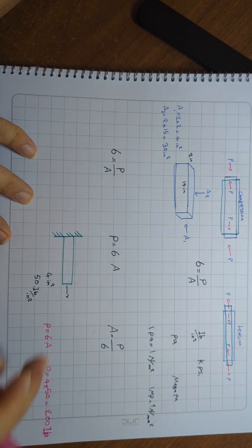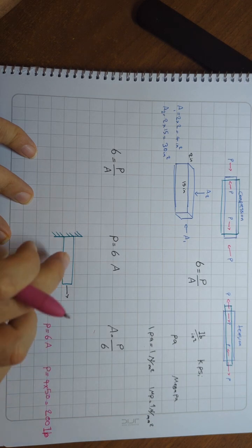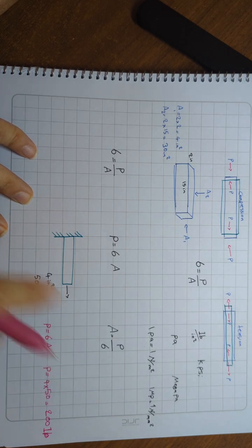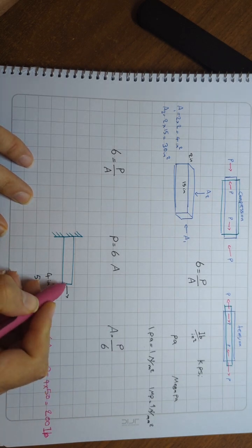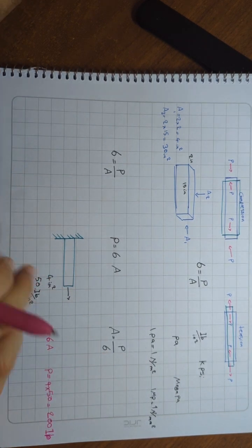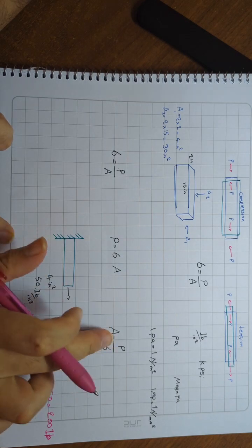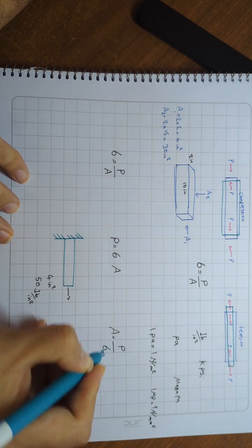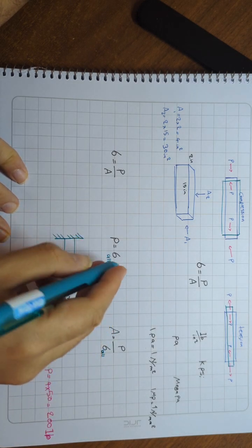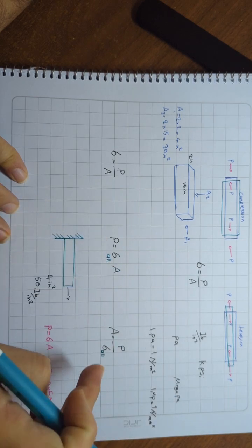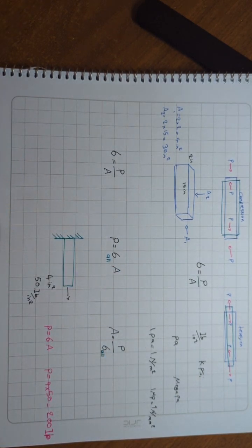But if we put anything under 200 pounds, this beam is not gonna break. Same as here. If we want to know how much should be the cross section of this beam so that it doesn't break, we use this equation. And that's why we call this sigma O. It means that this is the maximum allowable axial stress that we can have on this material.